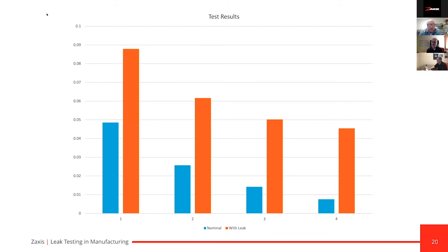When we actually fill the product, we're filling through a set regulator in the machine. We have 2 options that we can do, either a manual regulator or an electronic regulator. The majority of the units will have the manual regulator, which is a standard option. We set the test pressure by simply blocking the test port, either with a part or with your thumb if the pressure is low enough. And in the system, we can turn the valves that will allow air to go through the system and pass the pressure sensor.